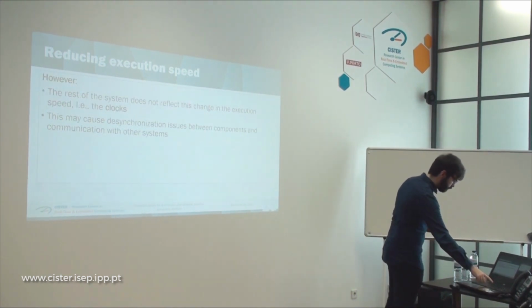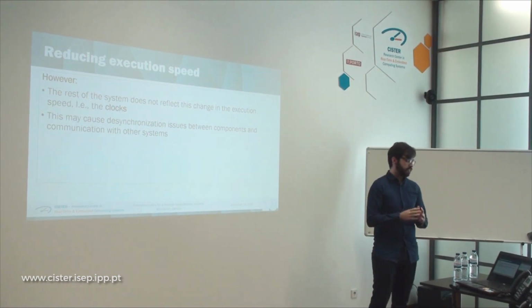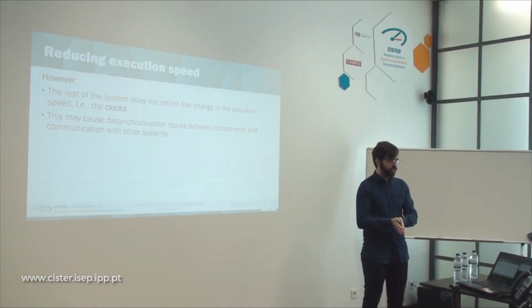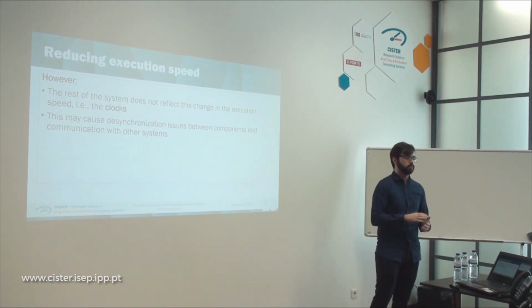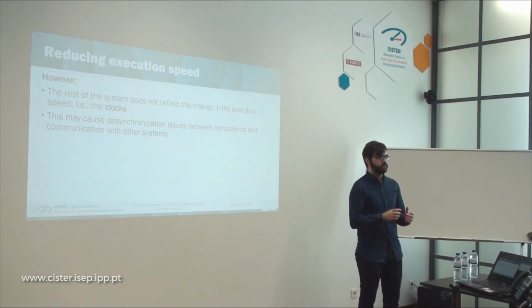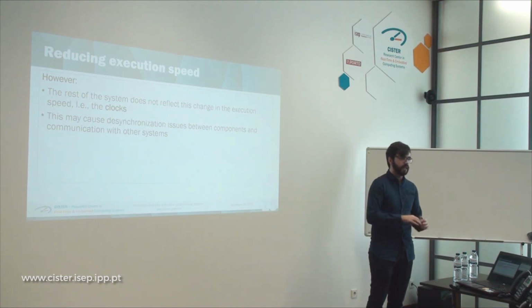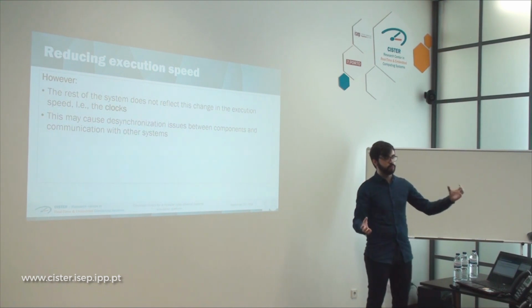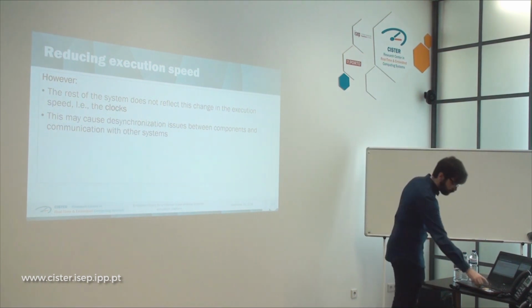So we took advantage of these facts and exposed the relevant pieces of this feature to be used as a command. However, this poses some problems as we've tested. The rest of the system does not reflect these execution speed changes, more specifically the clocks. Of course, if you have clocks unsynchronized, it may cause issues between the components, the hardware itself, inside that system, and if you're in the context of KhronoSim project, if you're using various systems to communicate with each other, they might have problems communicating because their clocks aren't synchronized.